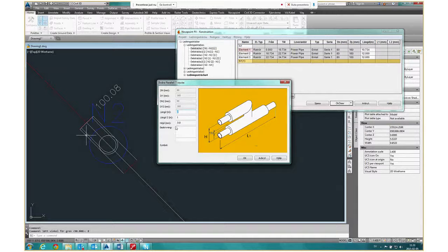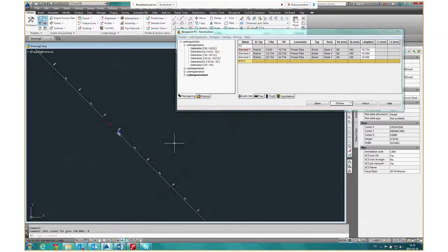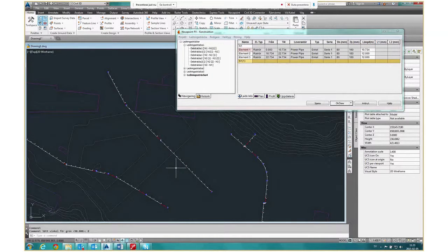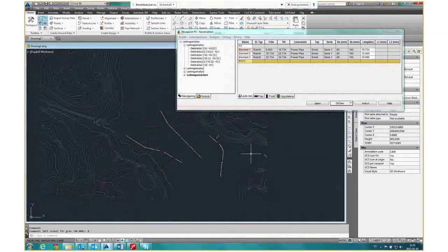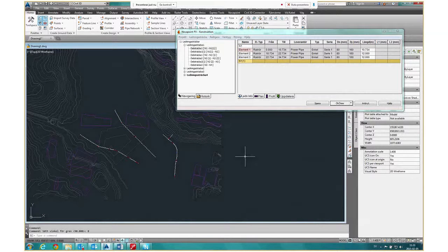Okay. Yeah, but these are the two different types of T-pipe elements that we have in the program now. And here you can also, if you have a negative value, get the stick under instead of over. So this is just an example of how you can work. But now we're in the construction dialog. We are outside the AutoCAD drawing right now. Even if we draw in AutoCAD, we haven't drawn it to the DWG file yet.